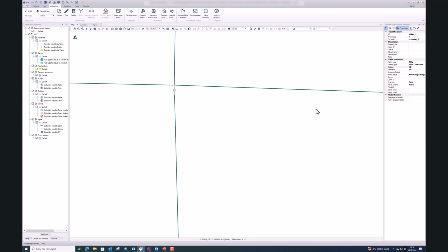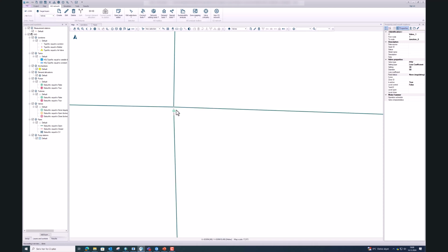And this is pretty much it for modeling pressure reducing valves. You can choose the status here to be open, or if you have two in a manhole, you can have the other one being closed, for example. But the thing that we normally have is that we have it regulating, meaning that it will act according to how the system is behaving, as we looked at previously with the 3 states that the pressure reducing valve can be in. And I think that's enough for now. So I think I'm going to leave it here.